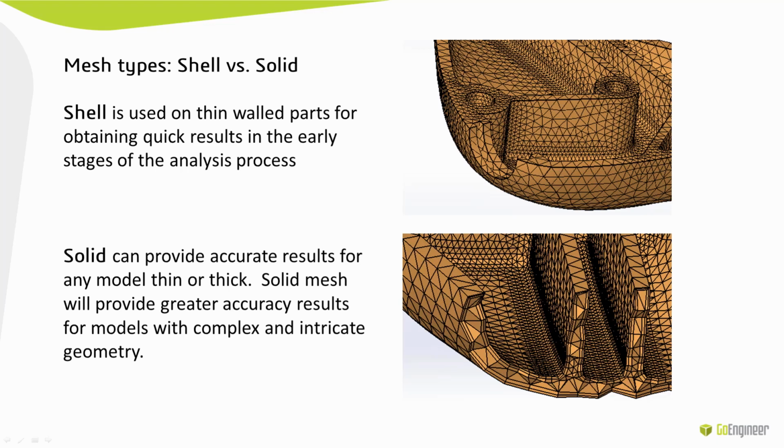I'll show you the shell mesh on this particular model that I've used in the software, and we can see the difference between the shell and the solid mesh and what may happen. And then a solid mesh can provide more accurate results for any model, thick or thin. So our solid mesh will provide a greater accuracy result for models with more complex and intricate geometry.